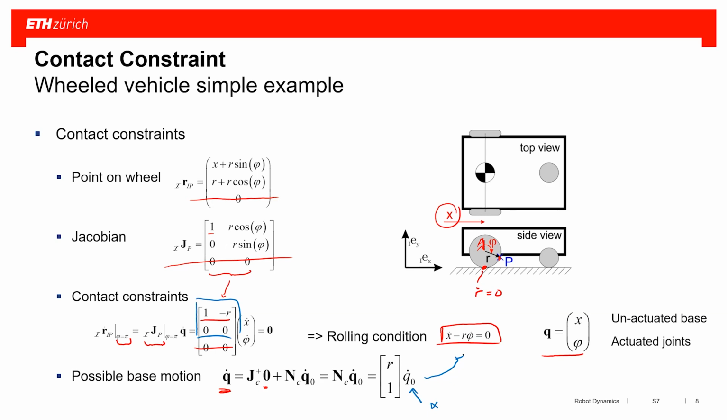So we can immediately spot this from the rolling constraint. We immediately spot how these joint angles are related to each other such that the constraint is valid and we can move. It's a little more tricky for a legged system or a complex robot arm, which has a contact constraint that imposes constraints on all the other joints. And then you have a certain way of how all the other joints can move without violating it.